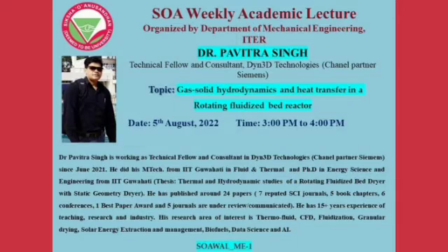So this is the procedure actually for the simulation. So I have selected a transient model because the velocity is very high. I have already calculated this by using the Reynolds number. This means the gravity effect is considerable because the particle has weight, so it will be minus 9.81, and I use the multi-phase Eulerian approach, and the energy equation is applied, so this energy is on.